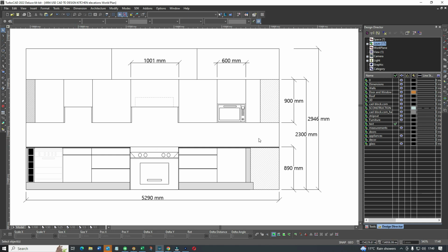So you need to start to understand the unit sizes: 300, 400, 600, 800. Not all the kitchen companies have the same units. For example, IKEA have widths of units that start at 400, 600, 800 and 1200. They don't do 1000, and they don't do 500s, and they don't do 300s. So when you're designing, you're slightly limited because of that. You go to, say, Wren or Howdens or Magnet, and then you're going to get the 300, 500, 600, but maybe they don't do the 400, or maybe they don't do the 800.